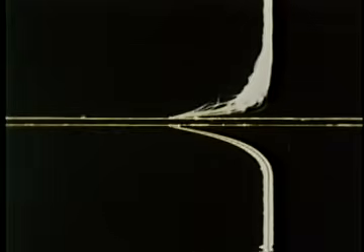In this photograph, we can compare mean laminar and turbulent profiles. Here is the laminar one, the turbulent one. And here they are superimposed. The velocity gradient normal to the plate is larger for the turbulent layer, and it therefore has a larger wall shear stress or drag.